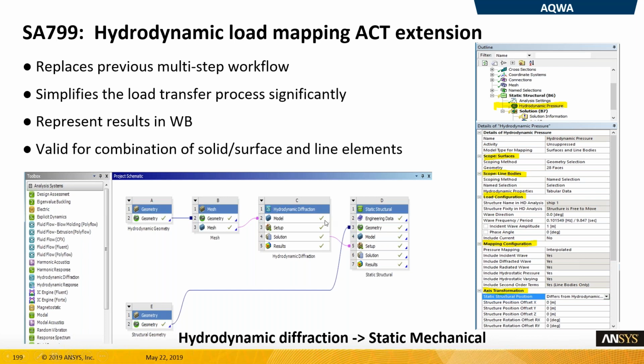In general, Aqua calculates the wave harmonics or wave loading on a structure, and then you can transfer this wave phenomenon into some kind of line pressure or area pressure on a structure with this FSI coupling, fluid to solid interface coupling.